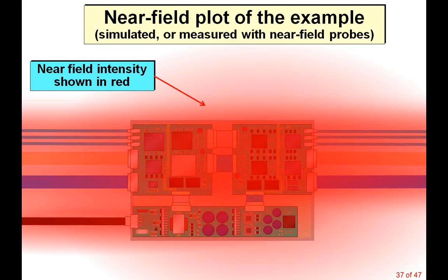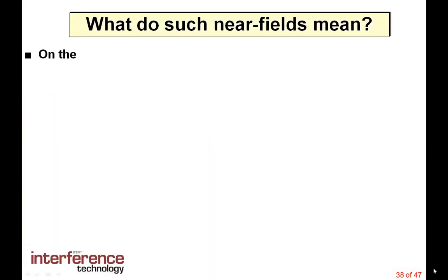We find that there's noise all over the place, all down the cables and near them too, all over the PCBs and near to them, strongest in these sorts of areas, but generally all over. What this tells us is that we have a lot of common mode noise leaking out, if you like, of the circuits.